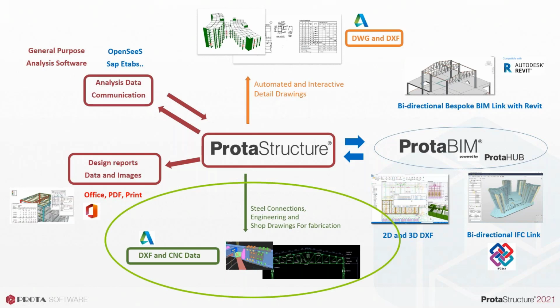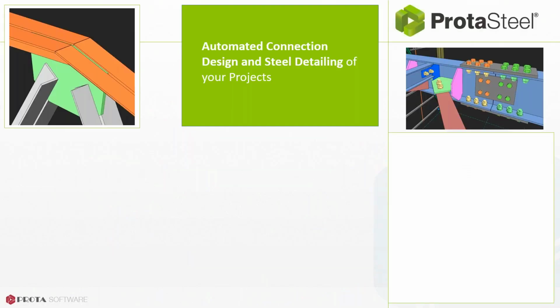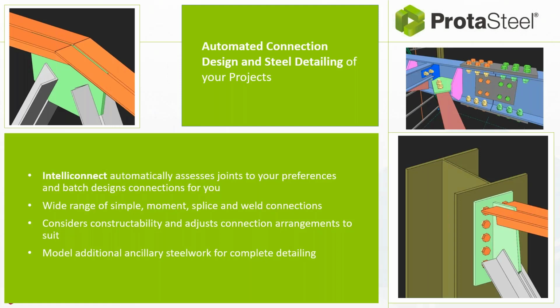Okay. Today we'll be focused mostly on ProtaSteel. I'll be doing a quick analysis and design on ProtaStructure. Then Mr. Volkan will take over. As you know, ProtaSteel is the dedicated tool for automated modeling and design of steel connections and creation of steel drawings like general arrangement, part and assembly drawings. And you'll also be seeing interconnects in ProtaSteel.